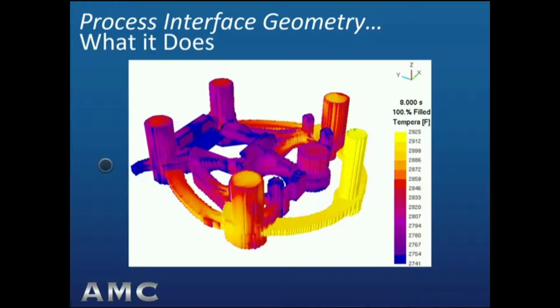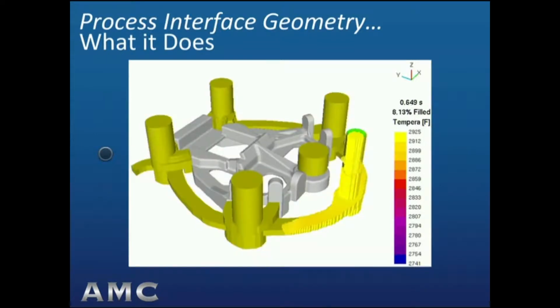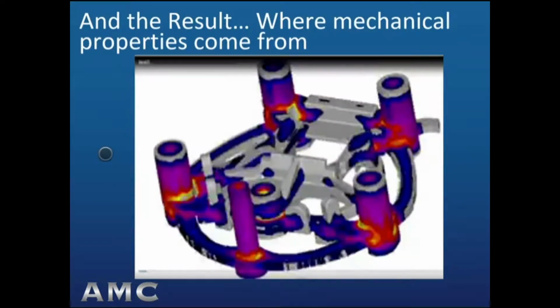So then, therefore, you're exchanging the shrinkage that occurs inside the casting for the volume of the risers, where the shrinkage can reside and not hurt anything. So let's look then at what the solidification of the casting looks like with this gating and risering strategy that we've now seen. Here we're looking in these blue and purple areas, primarily at the critical fraction solid, which is essentially a mushy zone, a combination of liquid and solid going on at the same time, in which it's critical because at a certain point the casting can still feed itself to solidification integrity at that critical point.